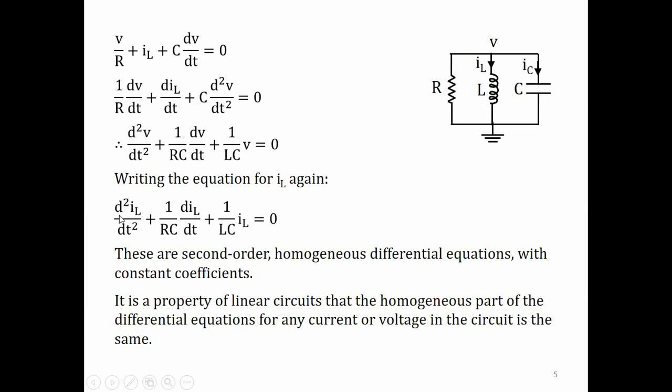I'm rewriting the equation for IL again. And if you look at this closely, this equation is the same differential equation for V and for IL. Second order term plus 1 by RC first order plus 1 by LC into the variable. So this is actually a property of linear circuits.